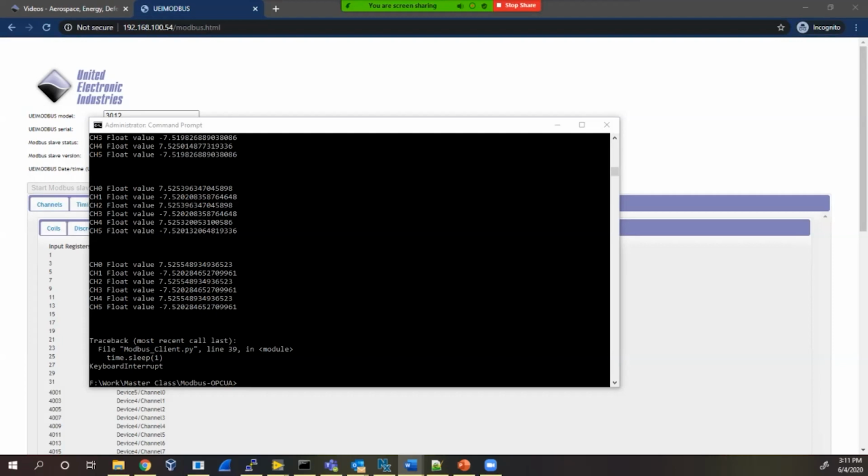Which of your boards are supported through Modbus and OPC-UA? Well, we'll get to OPC-UA, but the answer stands for both of them, that all of our analog and digital I/O boards are supported. I did mention in the slides, we do have an ARINC 429 over Modbus bridge. So really anything outside of the typical analog or digital I/O does require some customization, but it's not unfamiliar territory for us. Okay. If there's no more questions for Modbus, let's jump into OPC-UA.